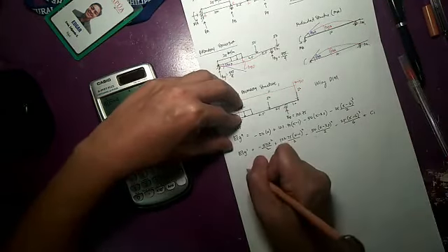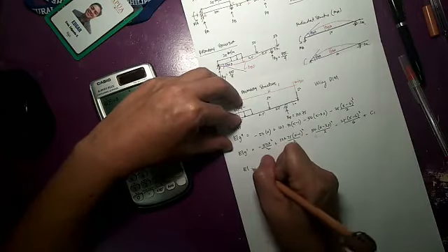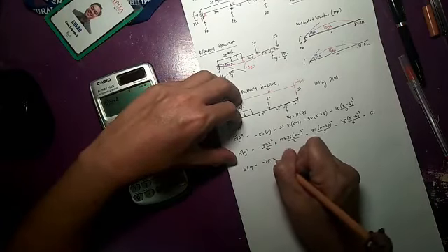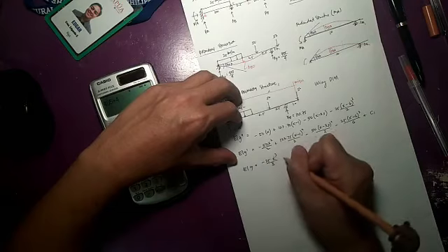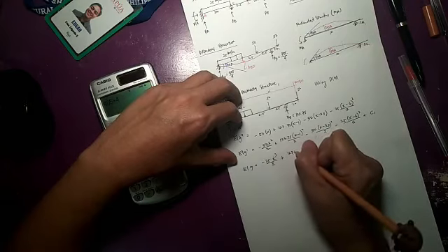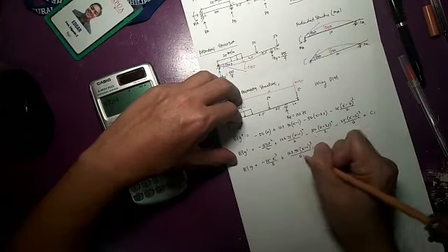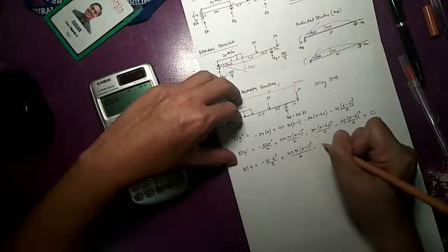Then the EI y, or the deflection equation, will be negative 25 x cubed over 3, plus 123.75 times x minus 1 cubed over 6, minus 25 times x minus 3.5 cubed over 3, minus 25 times x minus 6 to the fourth over 24, plus c1 times x plus the second constant of integration.